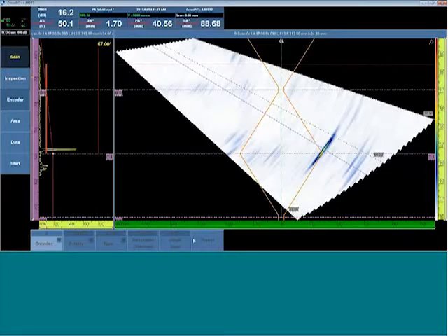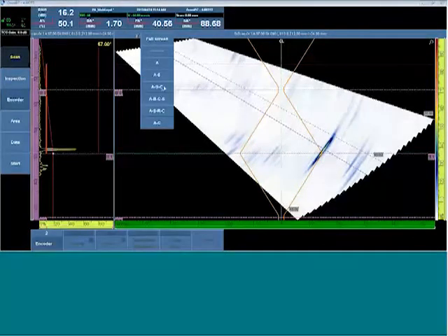We would normally always preset the encoder to 0 millimeters when the inspection starts. This allows us to also piece numerous welds together. If I were doing a 100-meter weld at 10-meter sections, I would be presetting file 2, 3, 4, etc. at 10 meters, 20 meters, 30 meters, etc. So whenever we talk about setting up the scan menu, we're talking about configuring the scan axes, always in blue, and it is the long axes of the B scan and C scan.